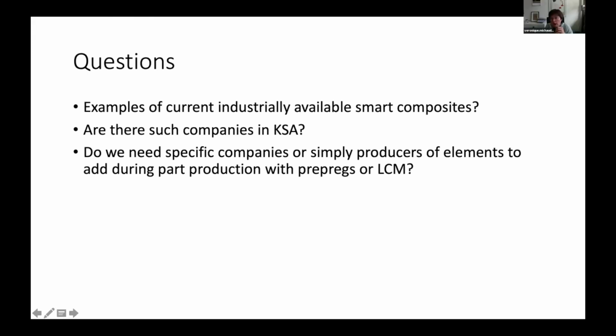Yes, but you have a little bit more flexibility in the fiber orientation, because you can really deposit the fibers as you want them. So you can really make some kind of topological optimization of the fiber placement. And then you can assemble even different parts that have different morphology. But it means that you need to have a mold, a press. So in terms of cost and everything, it's less practical for sure.